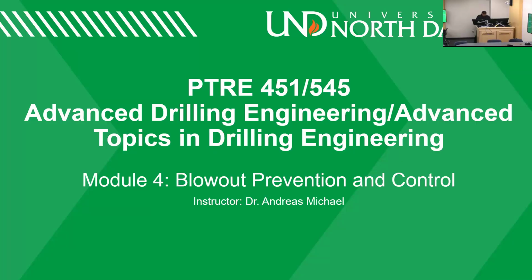You are reading DP pressure, that's your SIDPP, right? Mm-hmm. And choke pressure, the red, is your SICP. Yes. And they stay the same value all throughout? They do, yes. Okay, something weird. That would be the case if your kick had the same density as your mud.